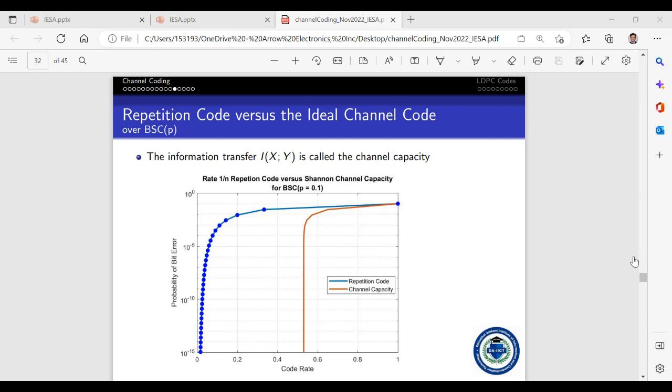I just mentioned that 5G uses LDPC codes and polar codes, right? LDPC codes are considered very good if the block length is very large, right? That efficiency ratio I was describing, R equal to K divided by N. So if K is large and therefore N is large, then the LDPC codes are good.